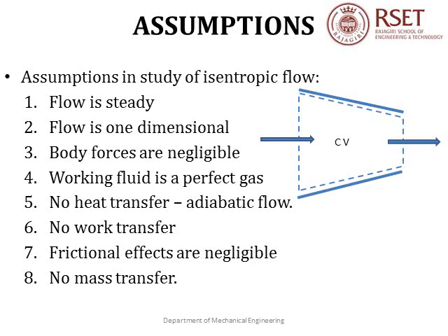There is no work transfer involved during the flow process. This is a flow of fluid through a variable area duct. There are no rotating elements that would be taking energy from the fluid or imparting energy to the fluid. Hence, shaft work remains 0.